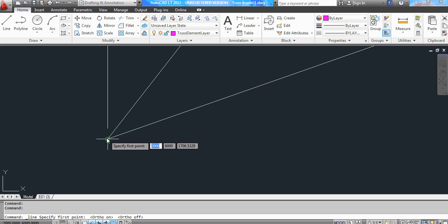The trusses must connect. One drawback in sketching the truss in AutoCAD is that sometimes somebody might think the points are touching when they are not. That is why you need your object snap on, because if the lines did not connect and you read off the lines, the software will just read the lines you have, and the truss will never be analyzed. It's as simple as that. If the truss cannot connect, then there's trouble. That is a bit of the advantage we have with the alias system I described in the former tutorial.